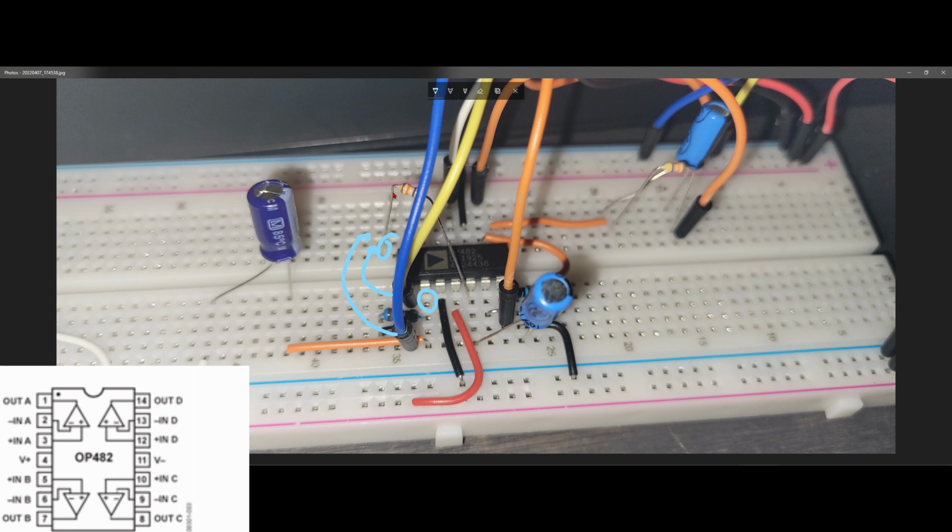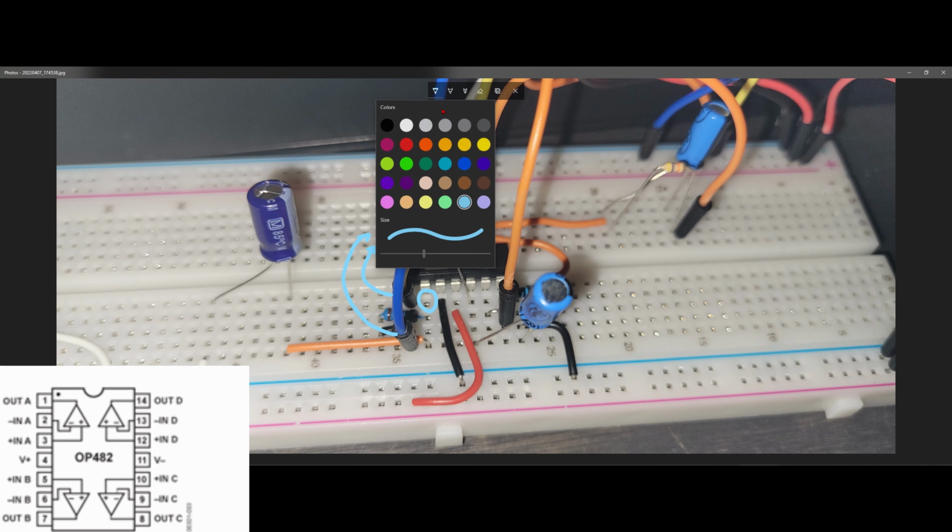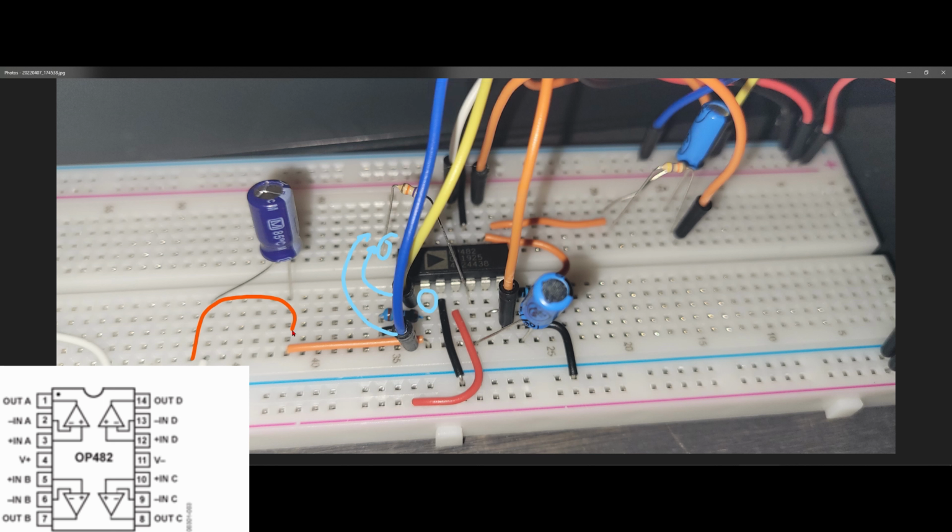The blue wire is to look at our input, because we have output, and the output was from here into here. If we look at the pinouts for analog discovery, we know that this first column right here is going to be our output. So that's our output for the first part. It's a little bit confusing, but basically we have the output for the first part, which we just looked at as the first column. And this resistor takes that output and pulls it to be an input for the second part with this capacitor right here for the low pass filter part.